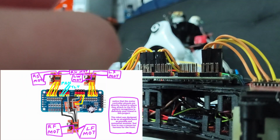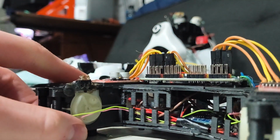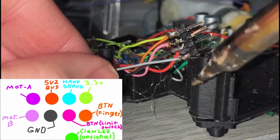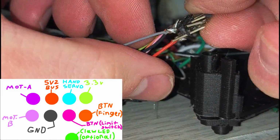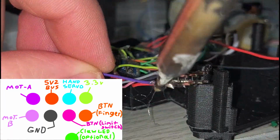It's also a really good idea to give everything a once-over with a multimeter at this point, because everything will explode if it's shorted. I'm going to go ahead and put a pinout on the screen so you can follow this at home. This is an 8-pin arm connector, and it connects to the arm to make everything easier to put together, take apart, and modify.